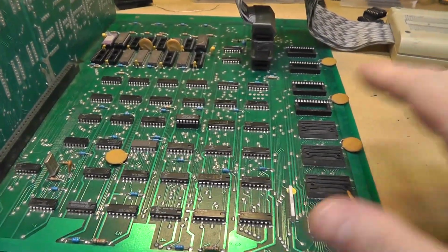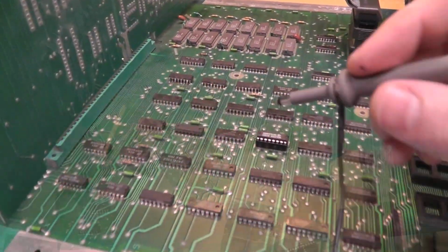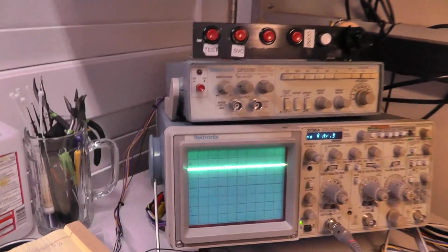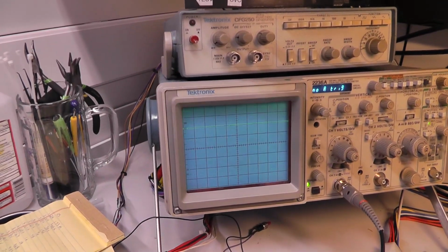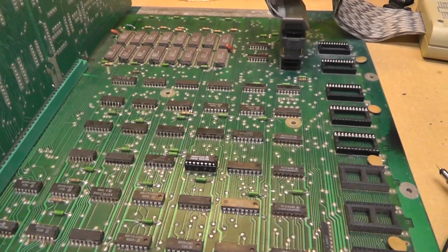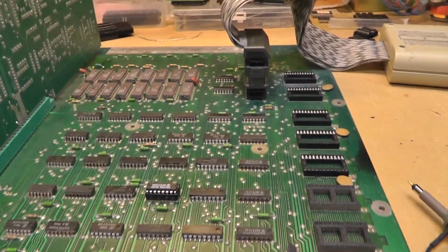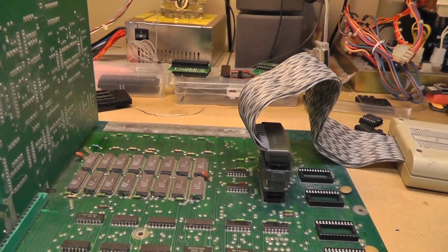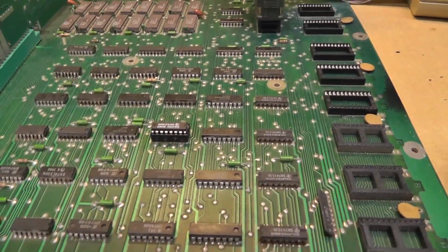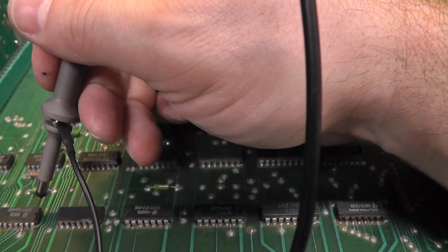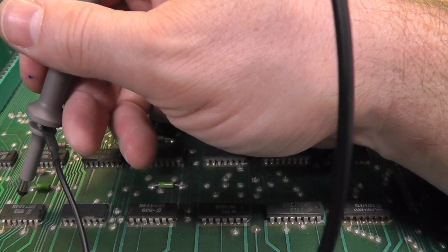So I'm going to hook up the other board and look at pin 15 again of this 166. Yeah, that's definitely a problem. I'm looking at pin 15 and it's just high. Let me trace that. I think that comes from A7, pin 8. A7, which is right here. 1, 2, 3, 4, 5, 6, 7.